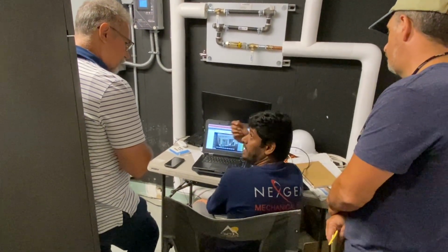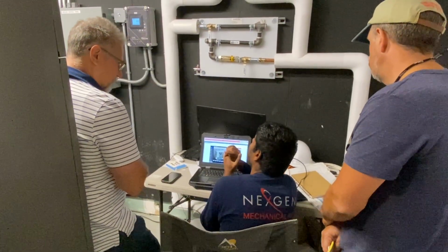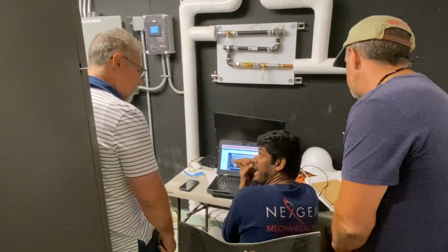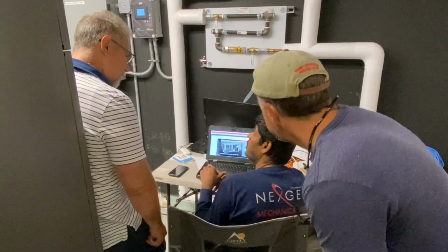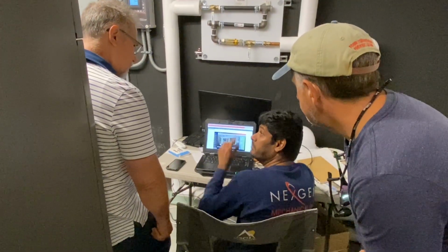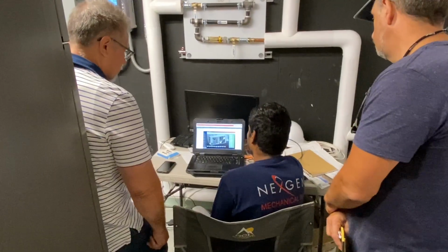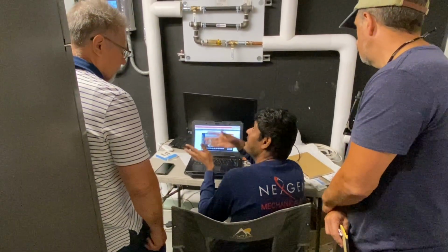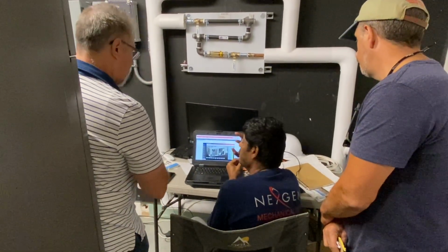So the DP sensor, the duct pressure sensor, and what else? We have the interim and of course we have the dehum mode. Dehum mode is again based on the average space humidity. If the average space humidity goes above a certain range, let's say for example 60%, then I'm going to turn on my dehum mode on my unit. Okay. Dehumidify. Yes. If it subcools, then my gas heat kicks in. That is taken care of by the unit itself.